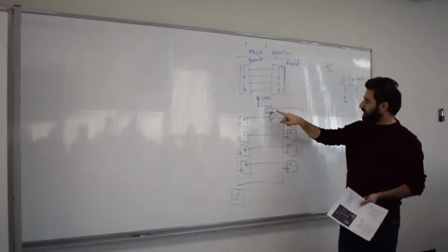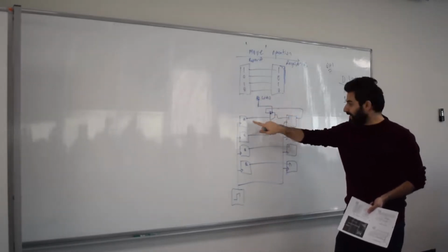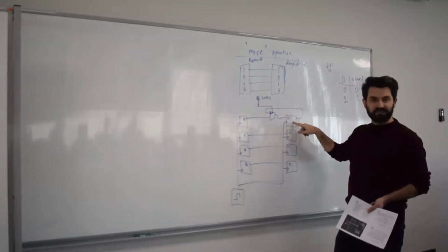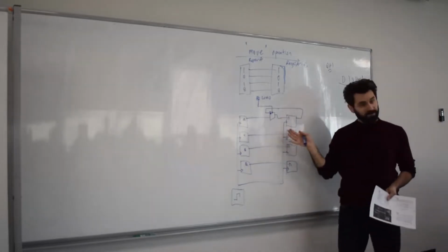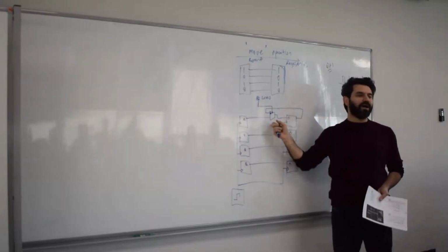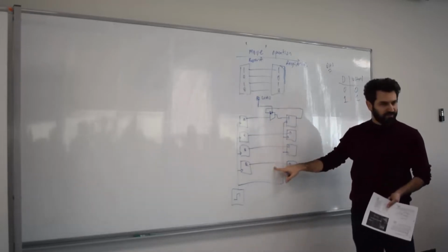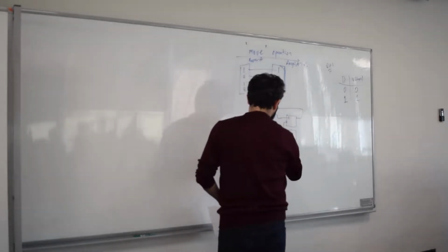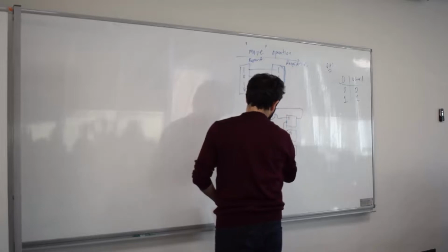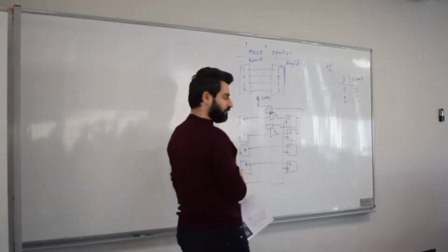So if load is 0, you store whatever you're storing. If load is 1, then the new value can be accepted inside the flip-flop. That's why I first wrote it without the muxes. Now I'm showing you why I am using muxes. And I have to of course do the same thing for the others because these are all independent. So I'm going to just draw a mux here again for the same basic reason. That's my control signal, and that is my feedback from the D flip-flop.